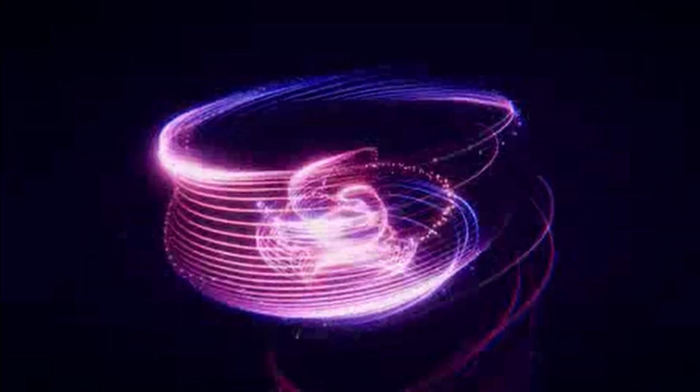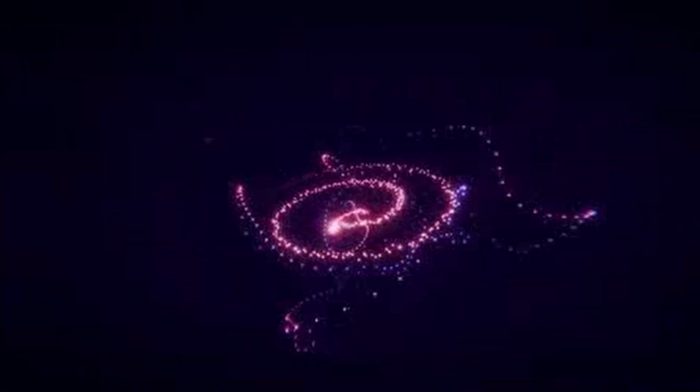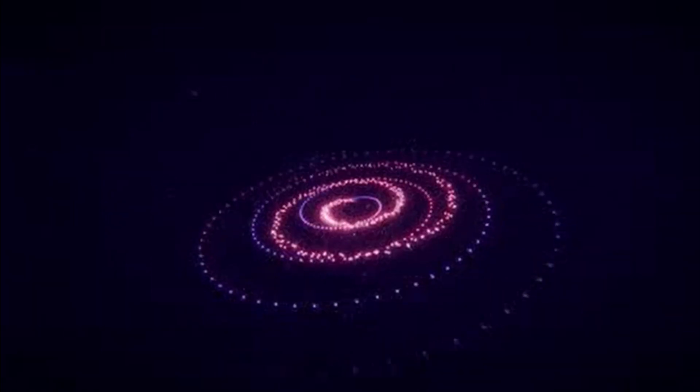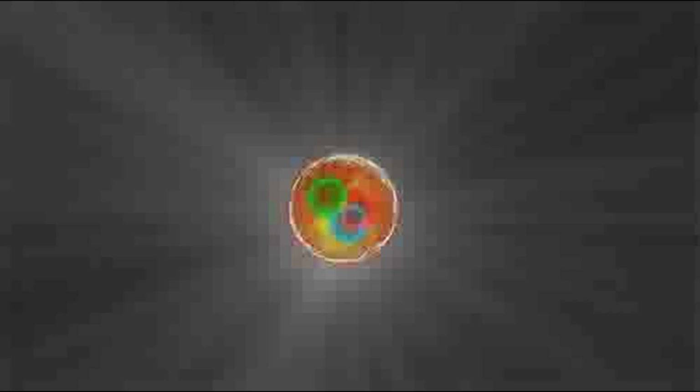2. Coulomb staircasing. One of the hallmark behaviors of quantum dots under the Coulomb blockade is the Coulomb staircasing effect. As the gate voltage applied to the quantum dot is varied, the conductance of the dot changes in discrete steps. This occurs because electrons can only tunnel onto the dot when the gate voltage aligns with the energy levels of the dot, leading to a stepwise increase in current.